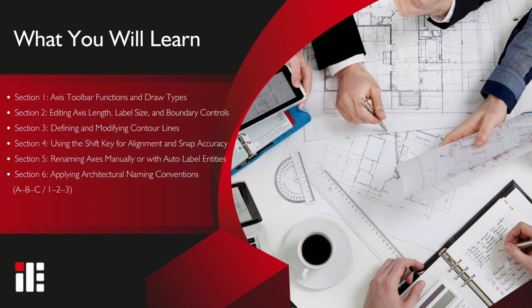In this video, you'll learn how to place and manage axes in ideCAD Architectural to build a clear and organized structural grid. We'll show you how to use the axis command, adjust insertion points, label settings and drawing types, and define axis length and style using the axis settings dialog.